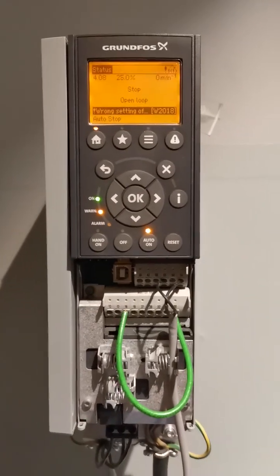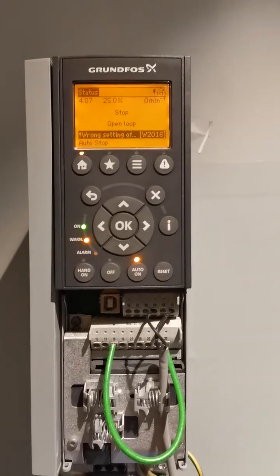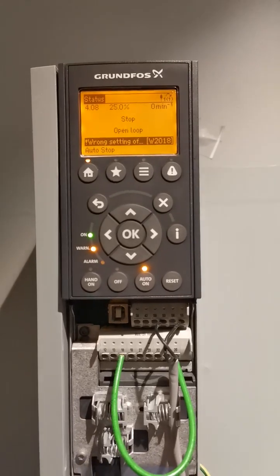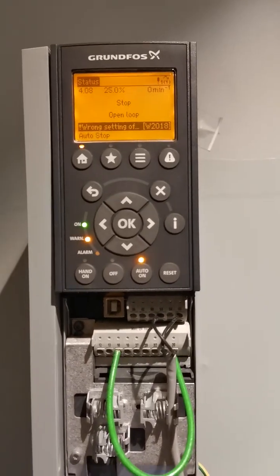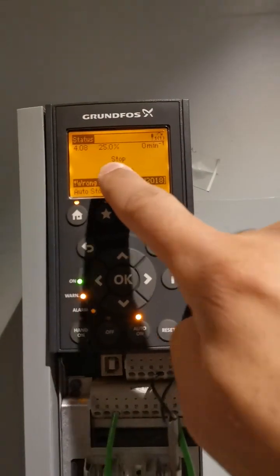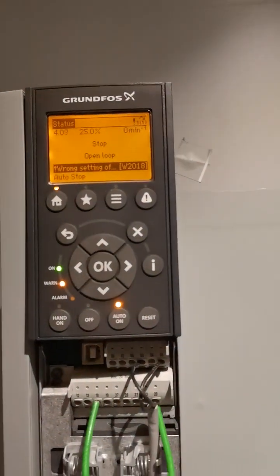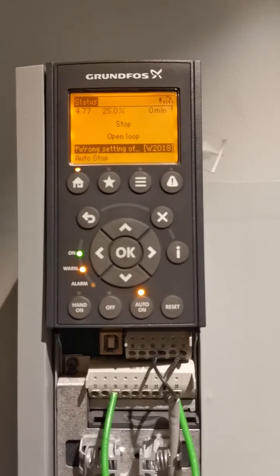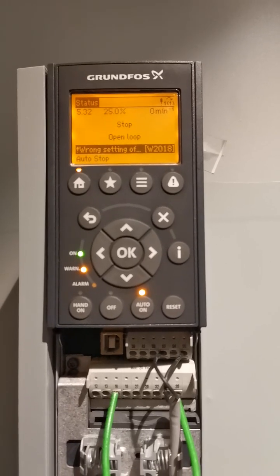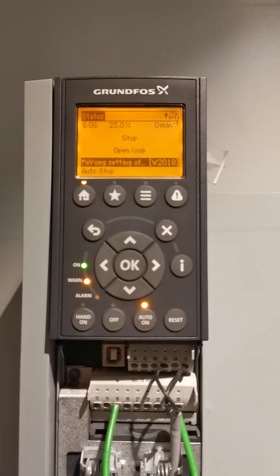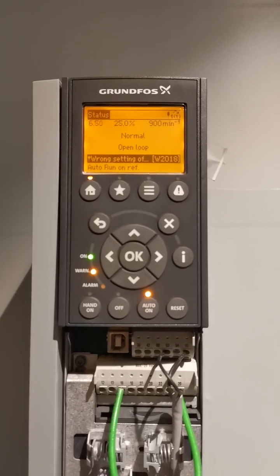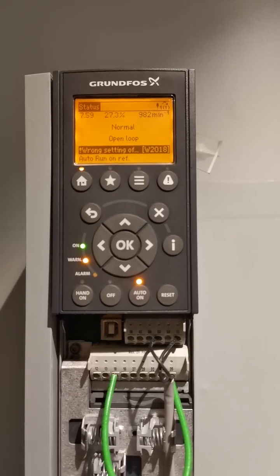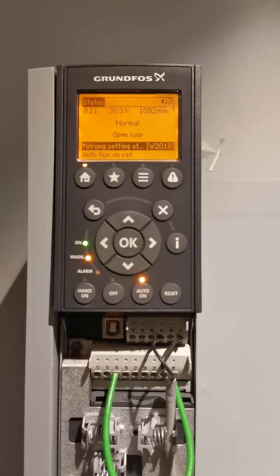Now I have already done the settings for the 4 to 20 milliamp signal. We just need to set the VFD onto open loop and connect it to terminal 53, which is the external set point. The motor is currently stopped because it is at the minimum value. Now if I start to increase the 4 to 20 milliamp signal, you will see that the VFD will start operating and go back to its normal speed, operating above the minimum speed of 25. All of these parameters are settable, you can adjust them.